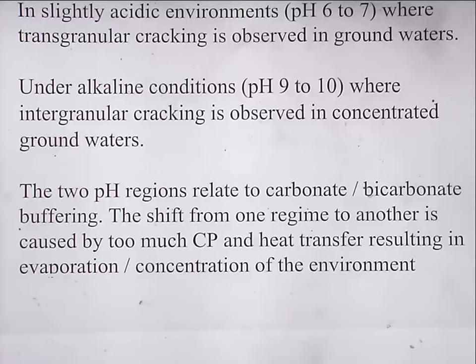The other thing, of course, is that this solution in here, not only is it low oxygen, but it starts to change composition. Remember, in the anodic reaction, you begin to produce acidity, because when you produce, first of all, some corrosion, so you get iron 2+ or iron 3+ or whatever the corrosion product is, and when that forms oxide, we want to form Fe3O4, so this is a mixed iron 2, iron 3.